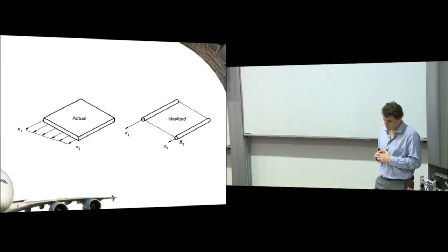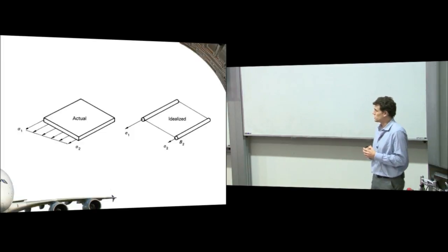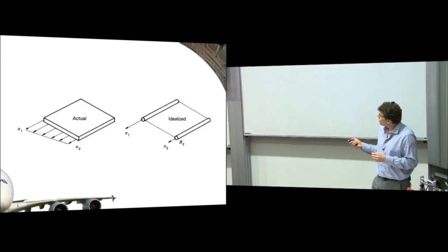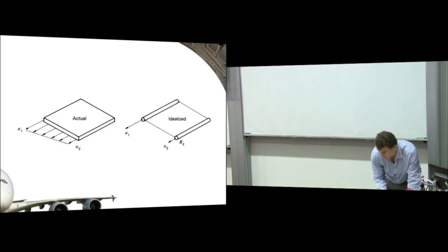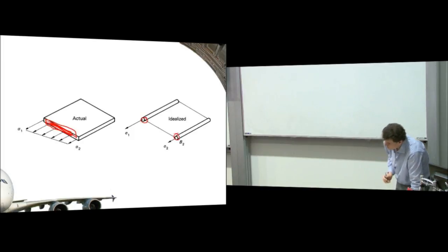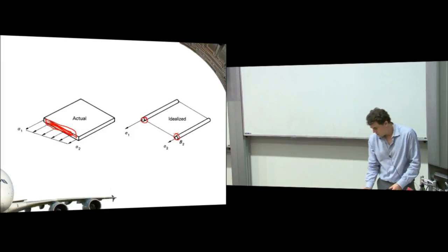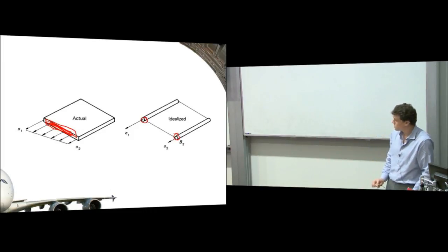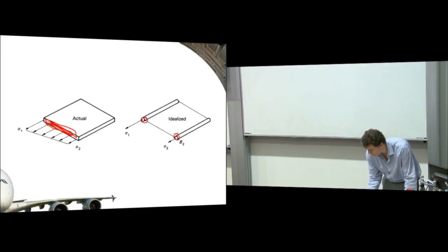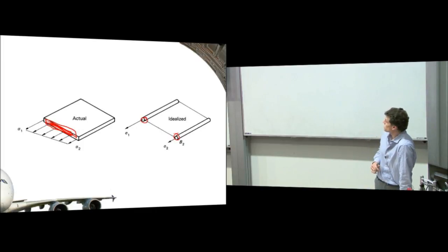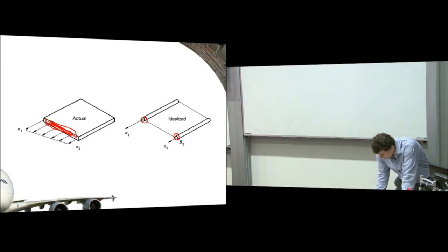And it's really an area idealization. So because we remove all the direct stress carrying area that's here, this cross-sectional area, we clump it into two booms. And the material in between, we assume, because it doesn't carry any direct stresses, there can't be any variation in tensile stress across that regime, across that distance. Now that solves a few problems for us.